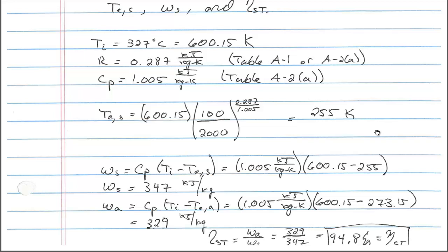And so, as time goes on, if that isentropic efficiency drops, that's an indication to the plant engineer that something is starting to go wrong with that mechanical device. Either a bearing is starting to go bad, or something isn't being lubricated properly, but it's used as diagnostic information.